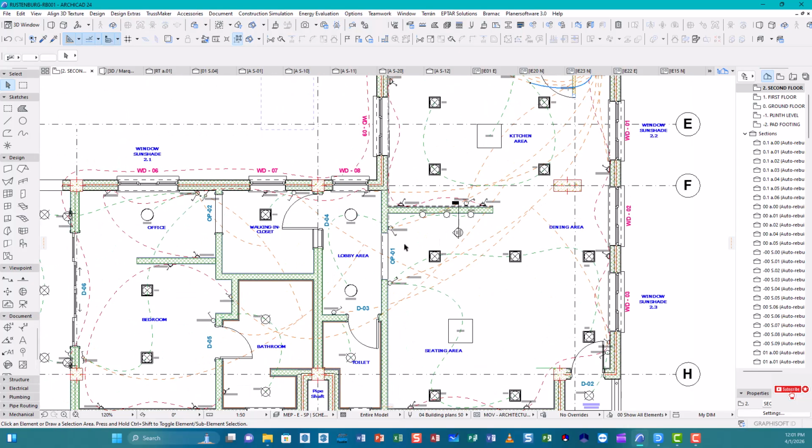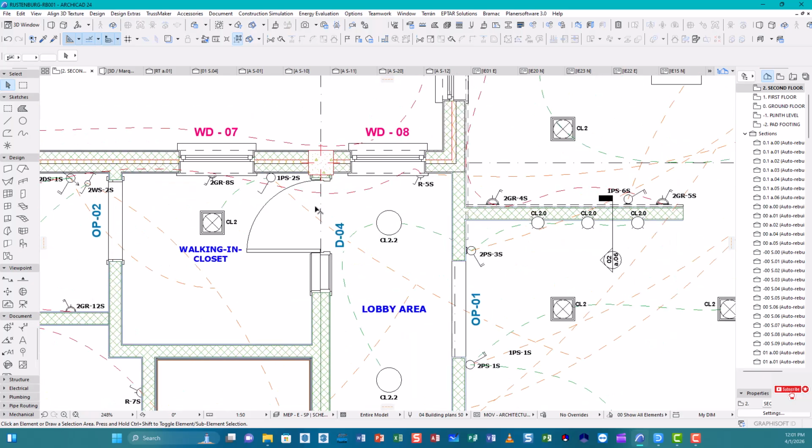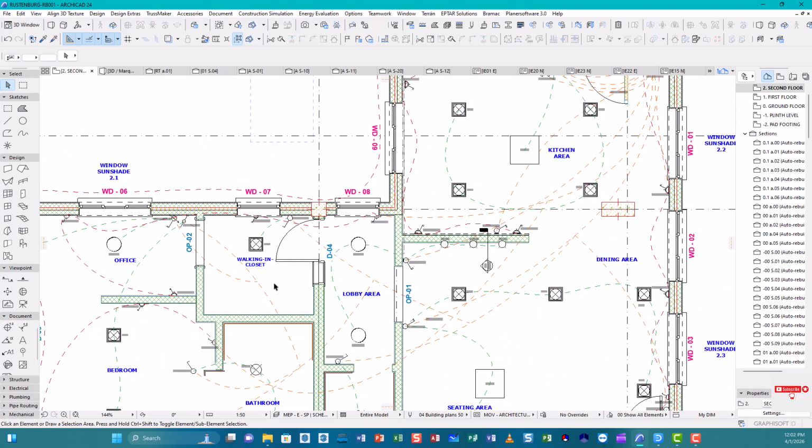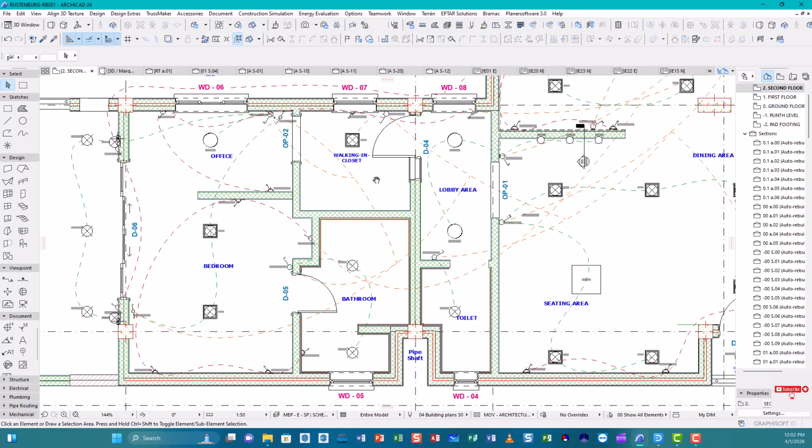What we're gonna do now is, we are done with the kitchen wiring and the electrical fixtures placement in the kitchen. So we're gonna take them to the other places. Remember, we set it up in parts, the 2D symbols and the 3D object. We already set each and every symbol. So now we will just drag the 3D object of the exact same symbol into place, to make them fit.